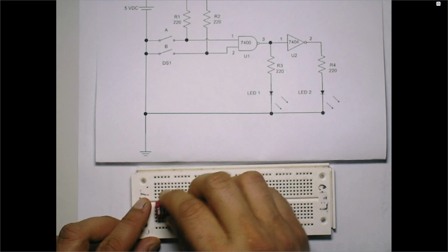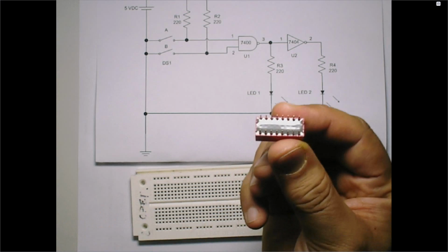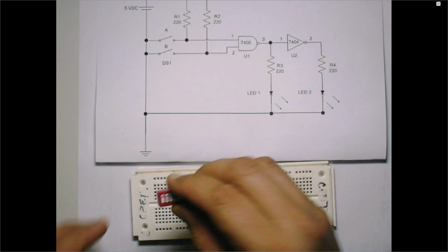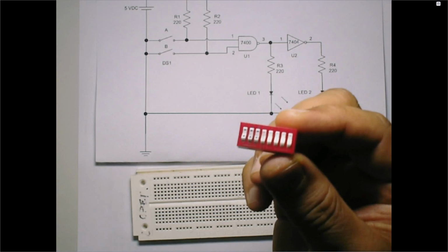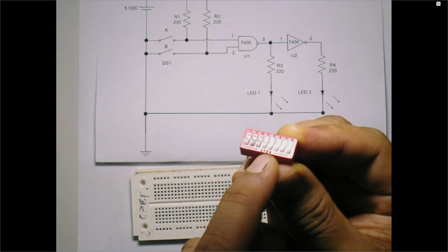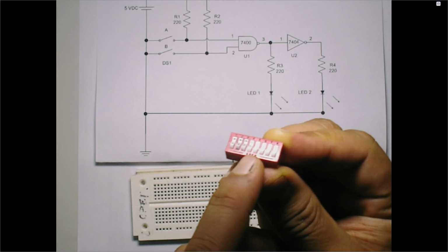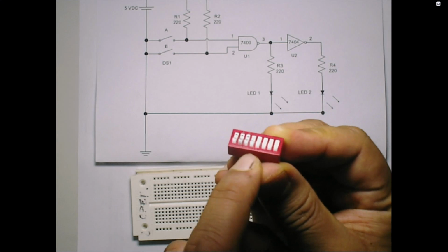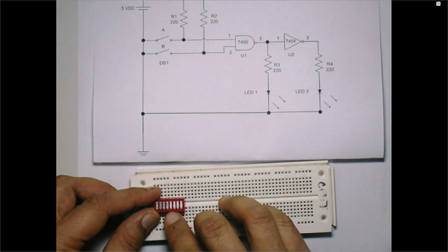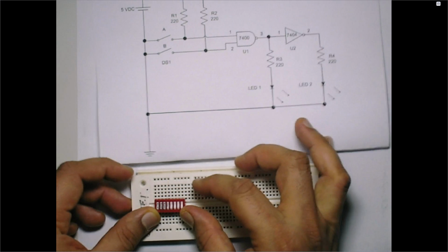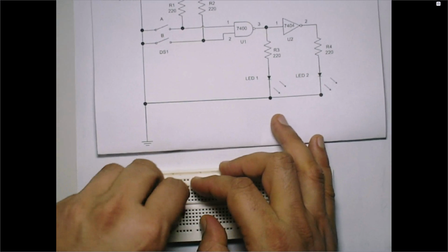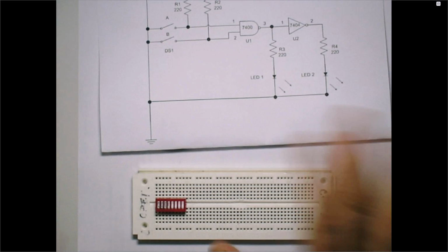I'm actually putting, you see, in the back side, there are two rows of pins, right? You see in the top row of pins, if you look very close, you might see something written here, right? It's written open. Do you see it? You probably cannot read it, but you can see there is something written, right? This is written open here. Now that open should be at the bottom, okay? So I kept the open here, and I'm pushing it a little bit, because if I don't push, it will not plug right. I pushed it, so the switch is already plugged, okay?